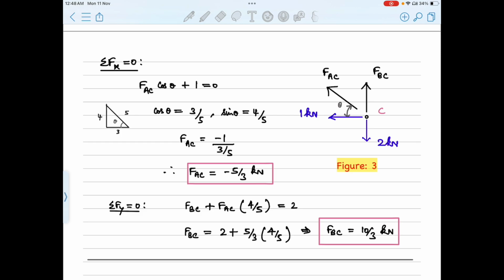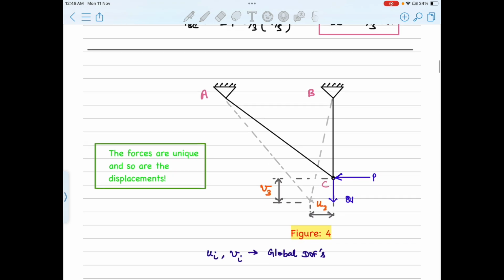However, we didn't learn it completely because only when the truss is statically indeterminate do we get to see how to solve for unknown forces by the force method. But we will learn it a little later. What are we up to here next? When we solve for the unknown forces in a unique way, the noteworthy point is the displacements associated with the structure are also unique. So one can think of approaching the truss analysis in terms of displacements rather than forces. Instead of choosing forces as unknowns, one can choose displacements as unknowns and solve the problem.